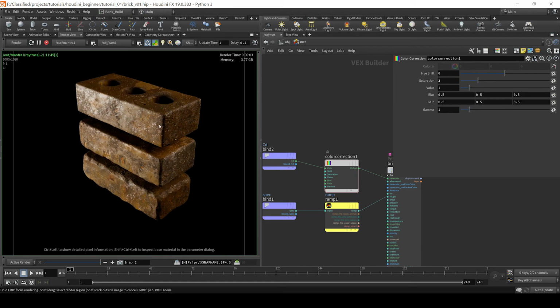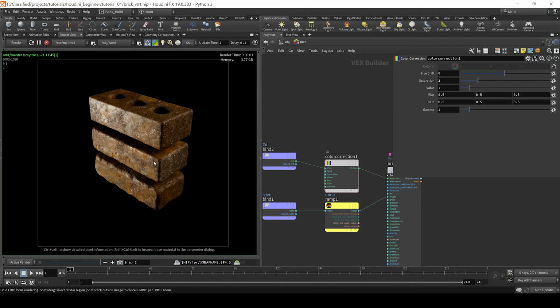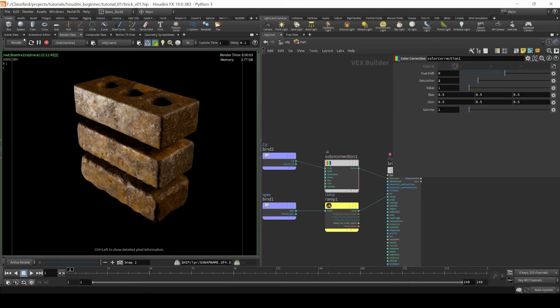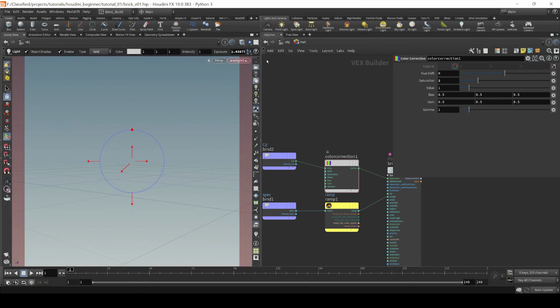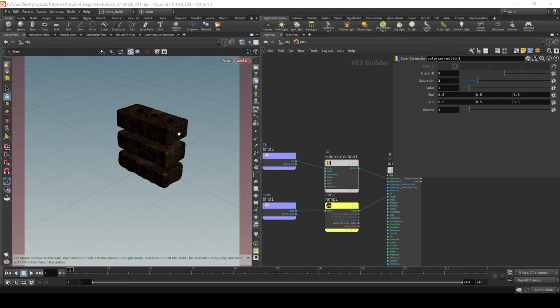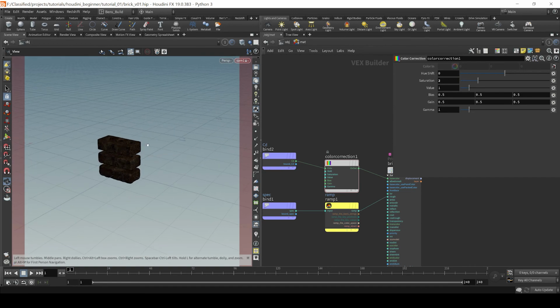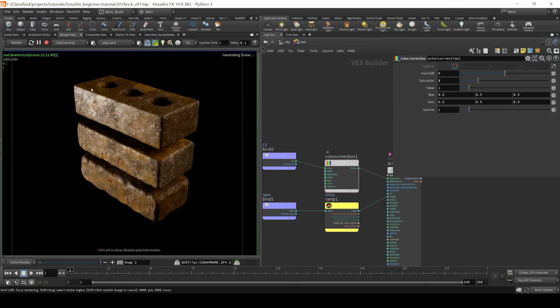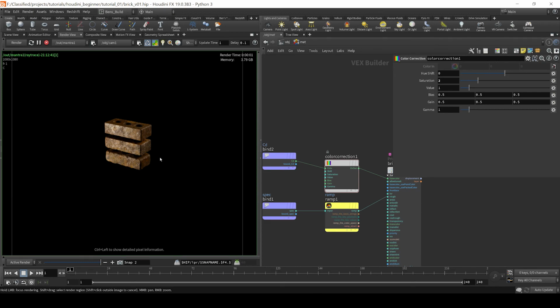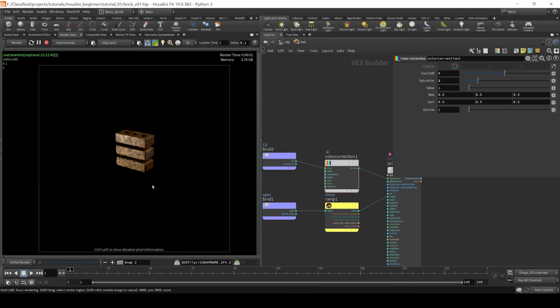And again, if you want to change out the texture, you can totally do that. This was my approach to just quickly coming up with a brick texture, because if I pause this here and select our camera and come back way out here, I'll update it. We see the farther we get away, especially, it just starts to look like grungy bricks. And you could totally change this up. You can make 10 variations on a damaged brick and cleaner bricks, and even do different textures and all this crazy stuff in order to make a really varied set of bricks.